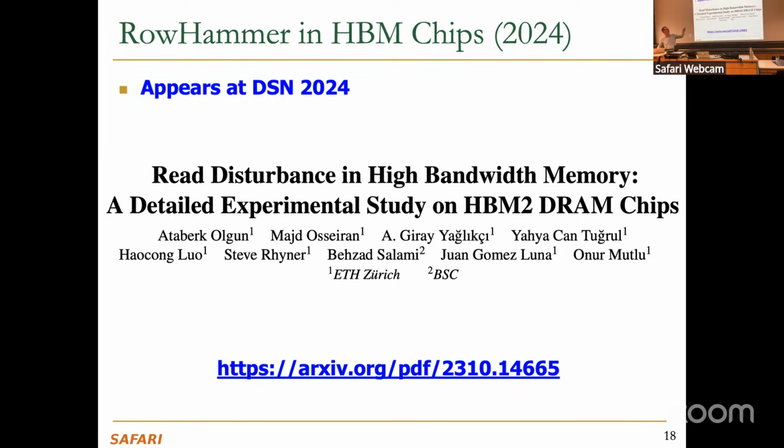For example, HBM2, HBM2E, they're supported by the FPGAs, but for HBM3, there's no FPGA that has an HBM3 attached to it, for example, today. At least it's not publicly available. So it's very difficult to do these studies and discover what's going on in the very latest chips today. That's true for DDR5 also. There's no FPGA where DDR5 is connected easily. So we're looking for ways of actually building that infrastructure to discover more about more recent chips.